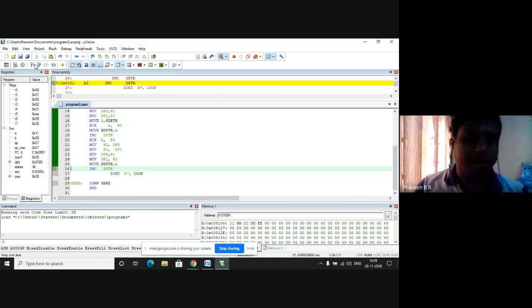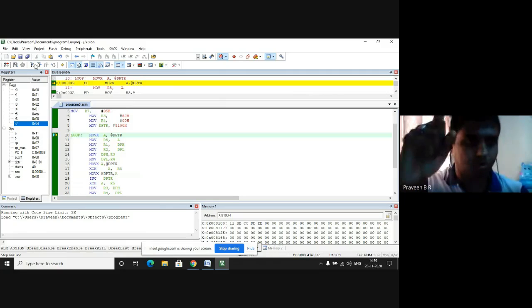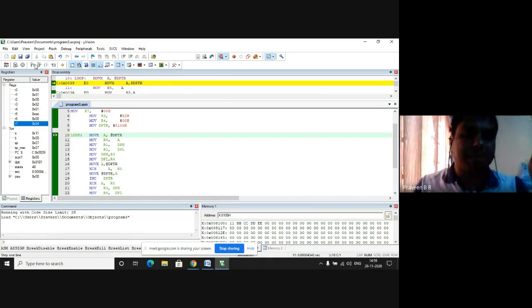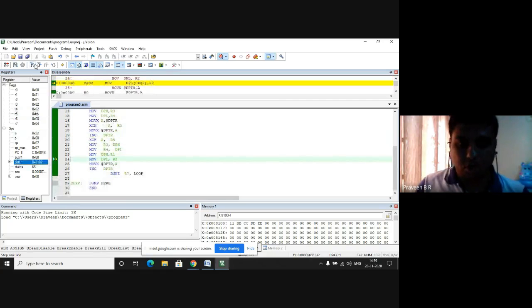Next, what I would be doing is transferring the next information. So before transferring, I'll increment to 8101. I'll compare whether the data present in the count is equal to 0 or not. I decrement the count because I have performed one transfer. I compare whether 4 is equal to 0. Since 4 is not equal to 0, it will go back and follow the same procedure for the second data to get transferred. So the second data gets transferred in the same way that I taught you just now.